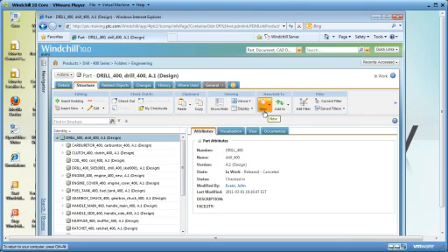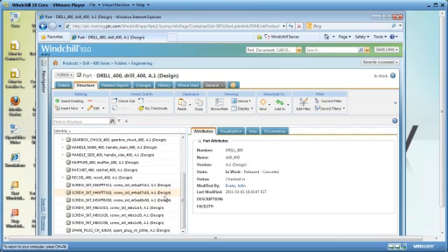So if I was able to hit my compare, which again, I don't know why I don't have that, what I would get is a CAD structure on this side, and anything that I have manipulated or changed on this side of the structure, it would highlight, this would turn red, and this one would turn red here, and over on the other side it says you have a difference in structure from one to the next. Now that might be by default, or by design, or by mistake, but it gives you the ability to view those structures and see the difference in those structures. Okay?